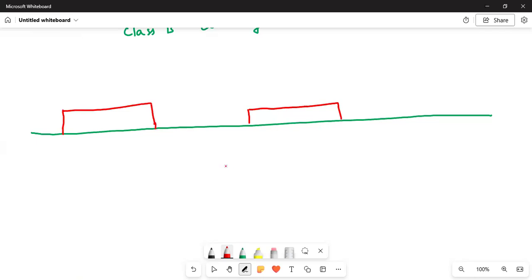It shall be placed such that the nose to tail distance, nose of this track to tail of this track, shall not be less than 90 meters. In this manner, you shall place the loading on the bridge. If you're placing one track, you cannot immediately place another. There should be a 90-meter distance. This is true in the case of a tracked vehicle.